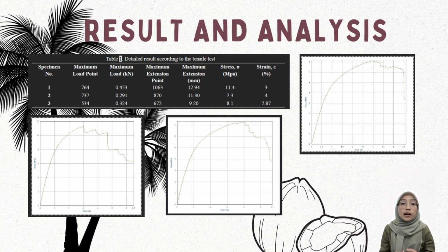Plate 1 has the highest tensile strength and can sustain the highest load-bearing capacity among the plates. This result proves that plate 1 is higher in fiber volume fraction, has greater bonding quality between the coconut fiber and the matrix, and has better manufacturing process parameters in curing and post-processing treatments. Hence, plate 1 is the best alternative for applications that need a high tensile strength and greater load-bearing capacity.